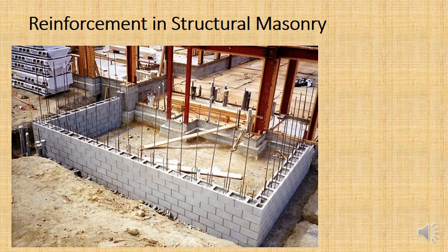So you can see here, this is a picture I took in Abu Dhabi. This was a site I visited, and you can see there that they're building the walls out of masonry, but you can also see that inside the masonry blocks they're setting reinforcing bars, and they're setting them in concrete inside the masonry wall.